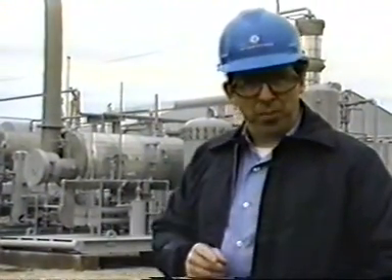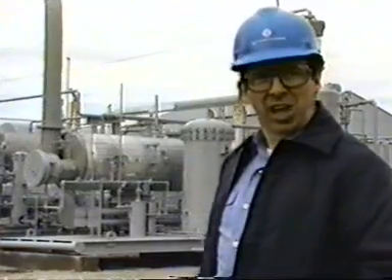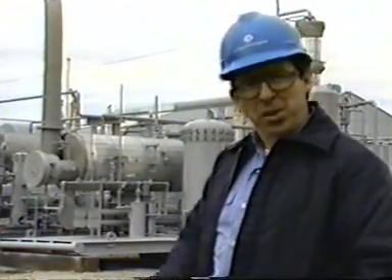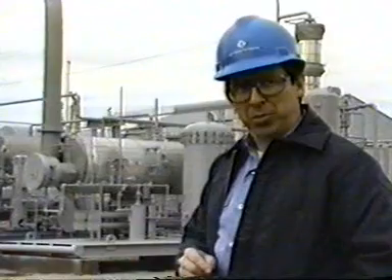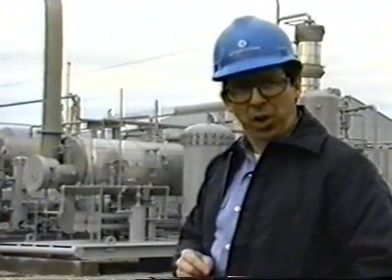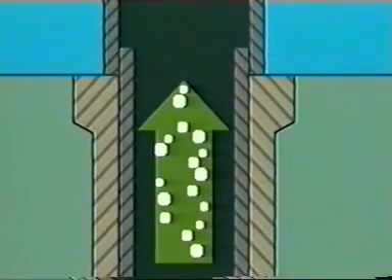If all natural gas came out of the ground in pure form, we wouldn't need this glycol dehydration unit. But almost all natural gas streams leaving the reservoir contain water vapor, and some even contain free water. As natural gas travels up the wellbore to the surface, it cools due to pressure reduction and conduction of heat to formation walls. When it reaches the surface, the natural gas is usually saturated with water vapor, and additional cooling